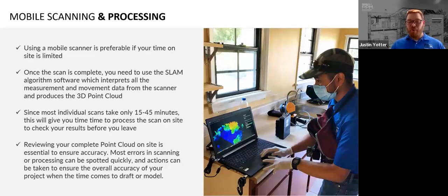Reviewing your complete point cloud on site is essential to ensure accuracy. Most errors in scanning or processing can be spotted pretty quickly, and actions can be taken to ensure the overall accuracy of your project when the time comes to draft or model.